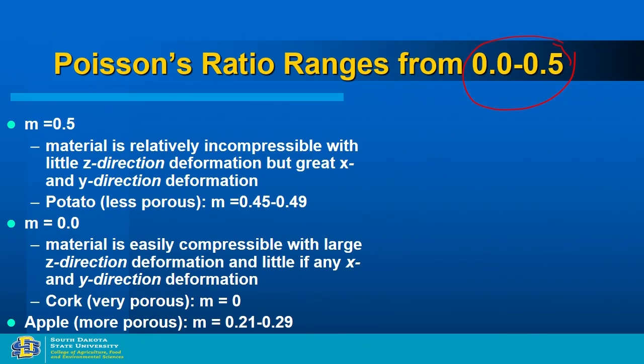If we have any expanded snacks, what about that? Expanded snacks, depending upon how much pore space you have. Cheetos will have a Poisson ratio of 0.1 or 0.05 because it has more spaces. Cheetos, right? Make sense? And then if it's a very dense product, Poisson ratio will be 0.2, 0.3 like that. Dense extruded snacks, things like that.